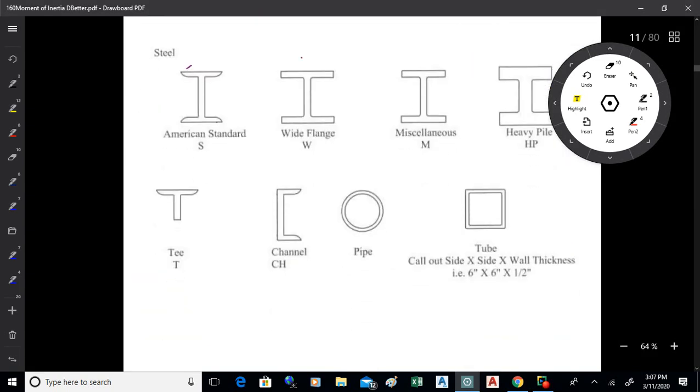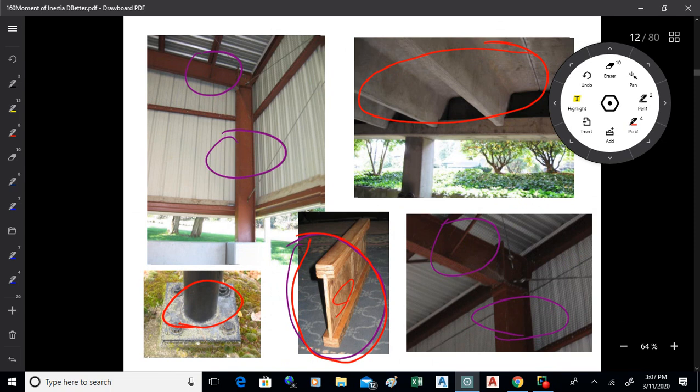All right, so shapes that have a high moment of inertia, when you look at their centroidal axis, the material for the shape is placed a long distance away from the axis. Okay, that's what you try and do to create a shape that has a high moment of inertia, is get the material out away from the axis. And that's how you get the most moment of inertia for the least amount of material, which is what you want to do with a beam. Okay, so we see these T's and I shapes, most particularly I shapes, used around in different situations quite a bit.